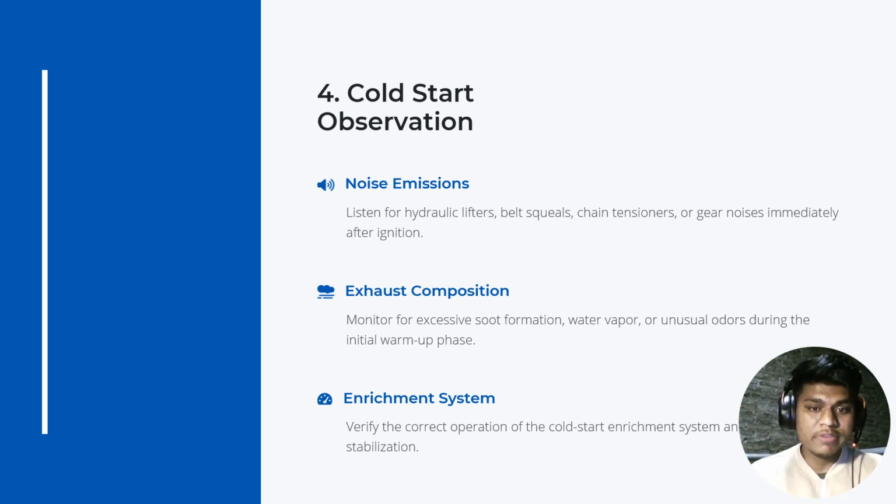A vital part of our assessment is the cold start process. Immediately upon ignition, we are listening for specific noise emissions such as the sound of hydraulic lifters, belt squeals, or chain tensioner irregularities. During this initial warm-up phase, I am also monitoring the exhaust composition for any excessive soot formation or unusual water vapor. This observation allows us to verify that the cold start enrichment system and the idle speed stabilization are operating correctly, which is a key indicator of the engine's internal health.